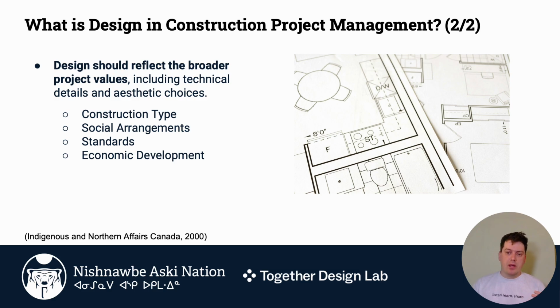And so again, here I might be pointing to a difference between a stick frame assembly, something built entirely on site using local labor, versus something that's maybe modular or panelized that prioritizes time efficiency. Again, there's no right or wrong there, but you're going to want to make sure in the project that you're reviewing that the assemblies match the goals of your scoping statement.